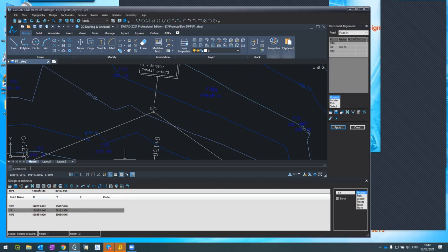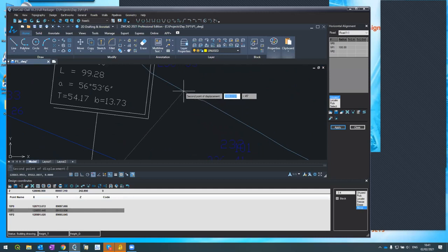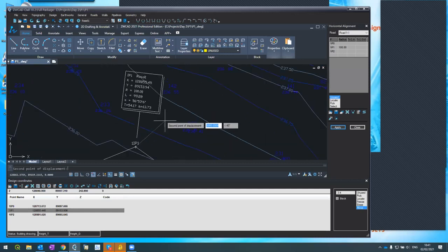I can do it manually, just type the new coordinate, or I can use the move here on the right. Move, go to the drawing, select the IP. Okay, fine, it was selected. Now it asks me in the command line, base point of displacement. I said from here. And where to? I can use object snap to move to this contour, or just free here.